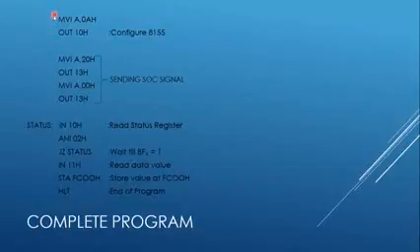The first 2 lines are used for configuring 8155 in the required mode. A small duration pulse on SOC input of ADC will start the conversion process. SOC input of ADC is connected to port pin PC5 of port C. So value 20H followed by 00H starts the conversion. Now ADC sets EOC to low at end of conversion.